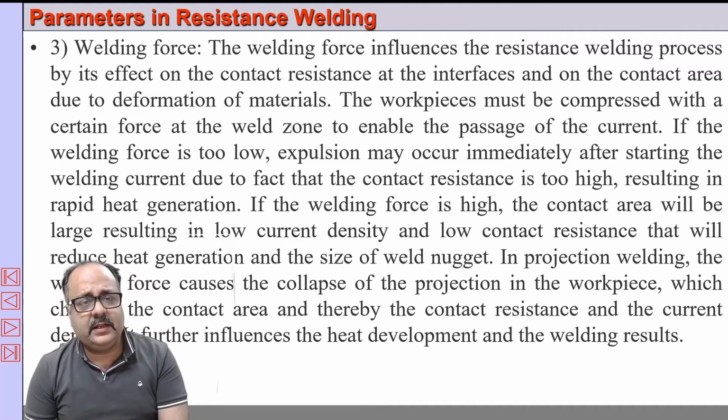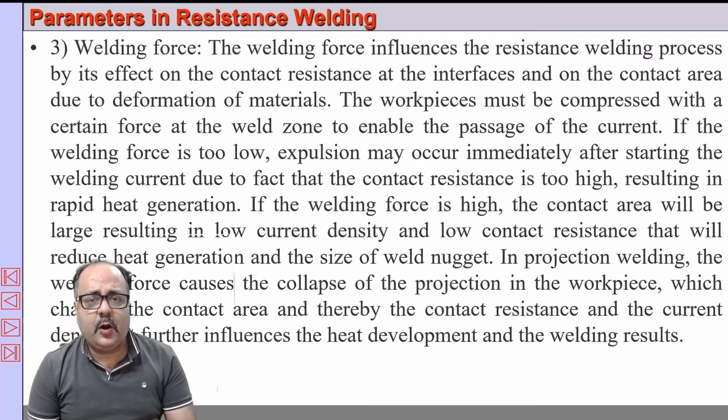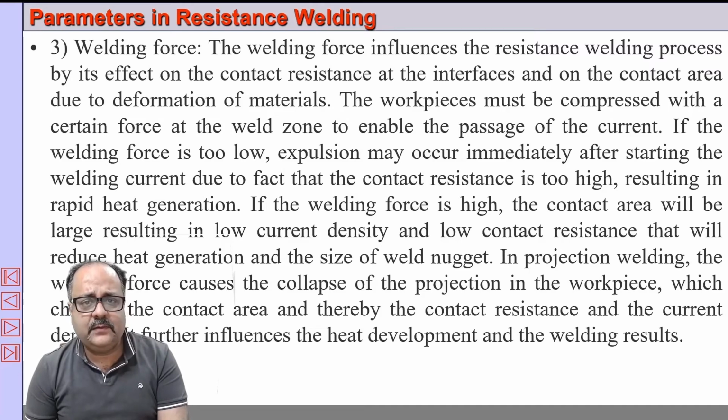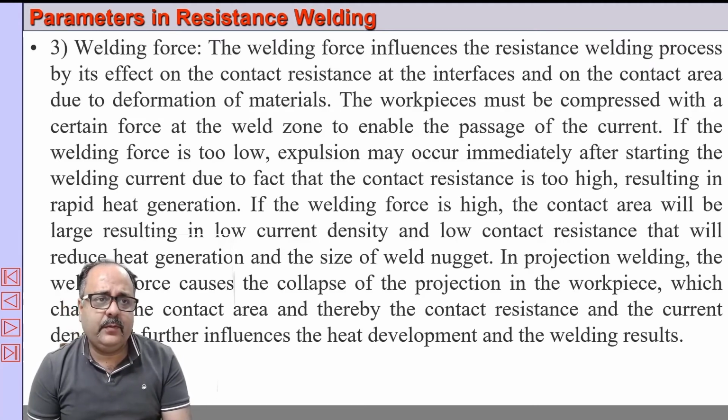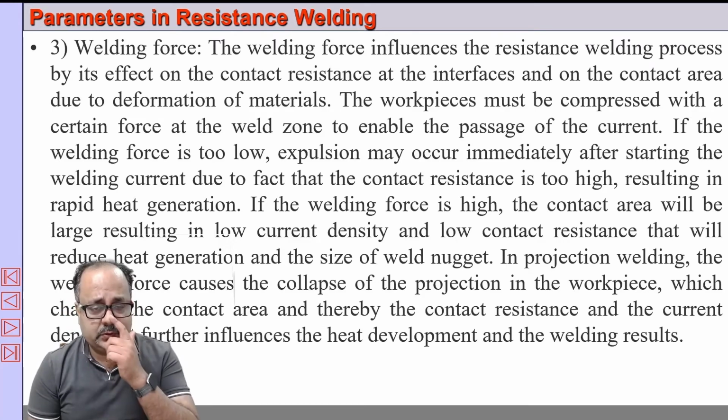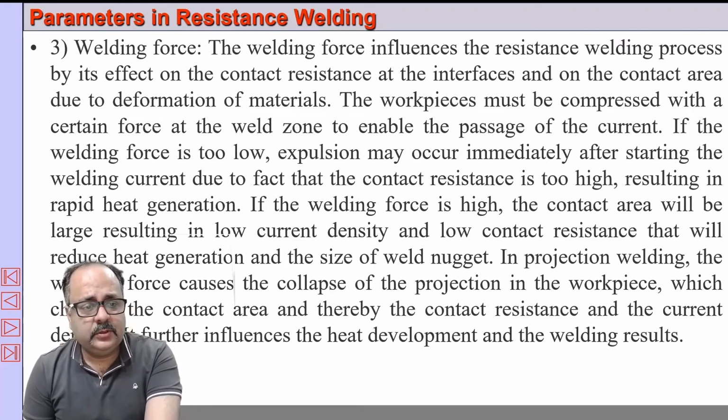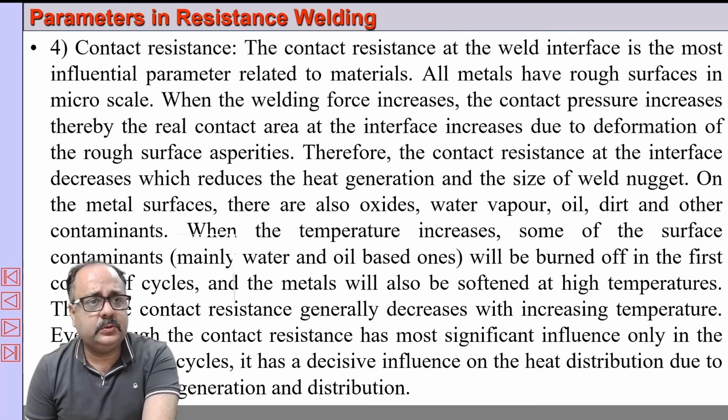This obviously will decrease the heat generation, and we do not want too low a welding force either. That will not give us a very good weld. So a balance has to be maintained between a low welding force and a high welding force. And high welding force, of course, will decrease the life of the electrode.